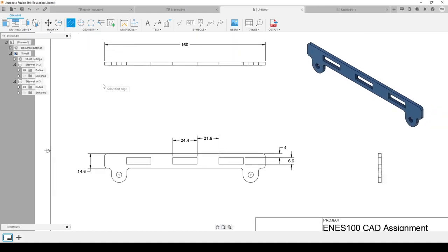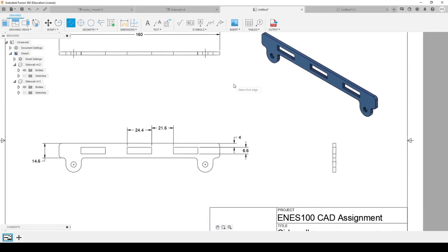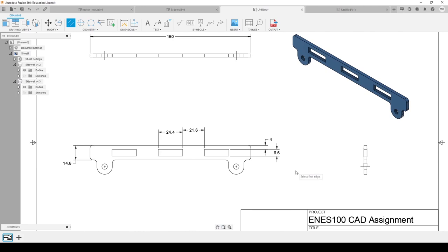We also want to do center lines to show symmetry or the center of a hole. So let's go ahead and put one here to note the center of that hole. Put one here. And these holes also correspond to this. And we also want to show that the entire part is symmetrical. So we'll show that here as well as here. And that's a little short, so I'm going to hit escape and extend it up and down. So that's demonstrating that it's symmetric. Cuts down on the amount of dimensions we need to fully define the part.